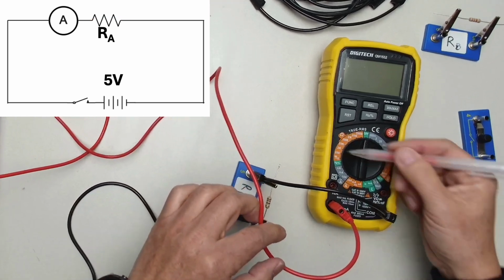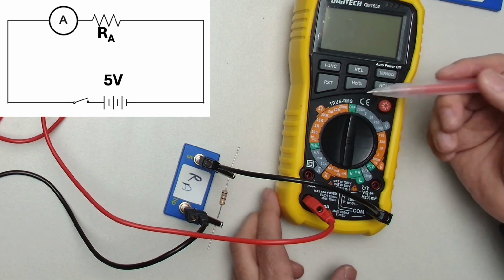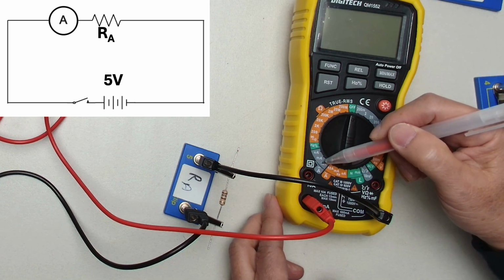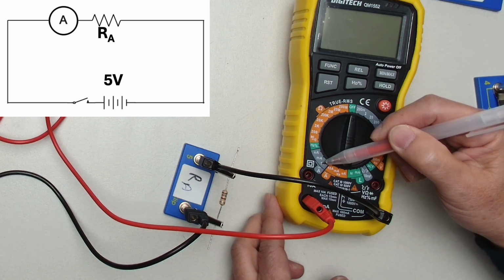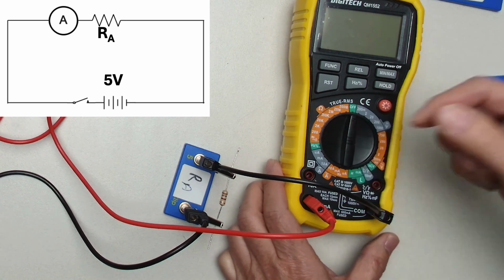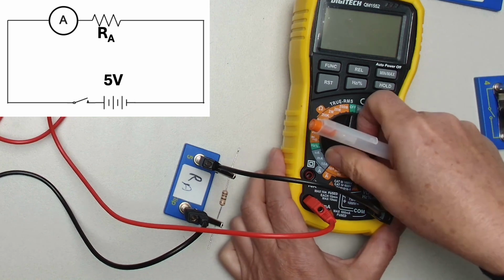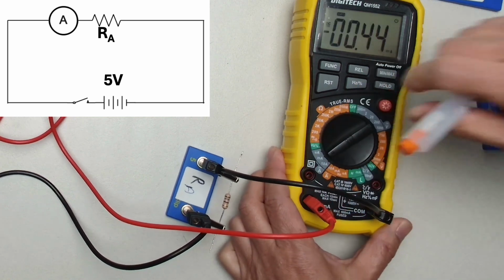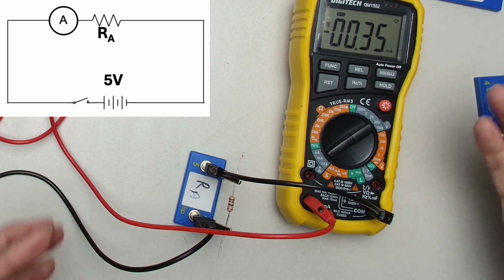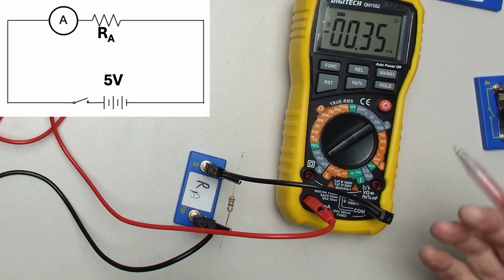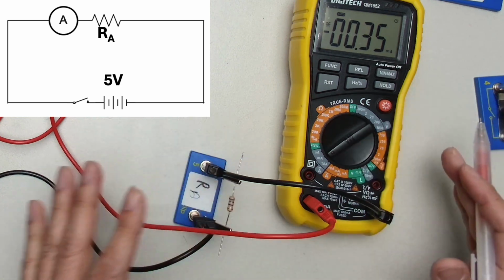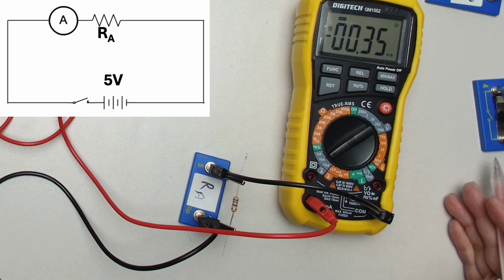Now, which one should we use? Remember, we are measuring current, so we are going to use either here or here. However, this is a DC current, so we expect we use this part. And we are going to measure mA, so I will choose this one here. Again, this number here is just because of the stray current or some sort of offset, whatever, don't need to worry. We haven't turned on the power supply yet.